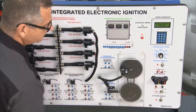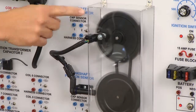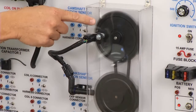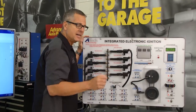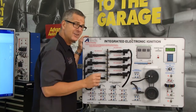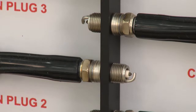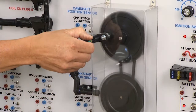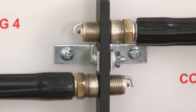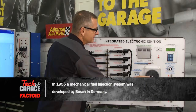You can see I have a crank position sensor and a cam position sensor. Now my crank's telling it when to start, and the cam could be telling it sequentially when to fire. Here's a tip for you. A lot of times if a car doesn't start, it's usually the crank. If I unplug that, you see all the spark goes away, it's not going to start. Now on the other hand, I can unplug the cam position sensor and it still fires. It just goes into sometimes multi-bank firing. It knows what to do to get the car running, limp home mode, but it'll get you there.